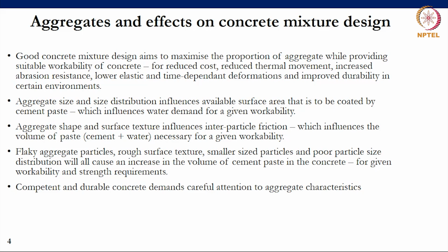Flaky aggregate particles, rough surface texture, small size particles, and poor particle size distribution will all cause an increase in the volume of cement paste in concrete. And this, of course, is for a given workability and strength requirement. Competent and durable concrete demands careful attention to aggregate characteristics, without which we will be in trouble to ensure that we produce suitable concrete for structures.